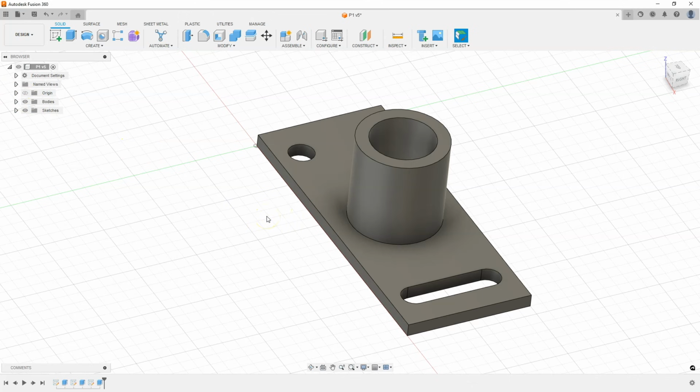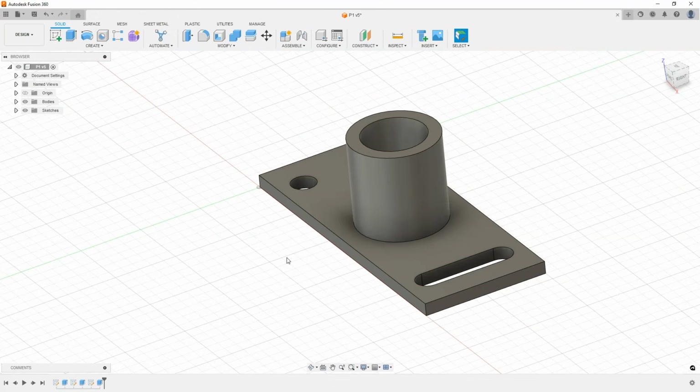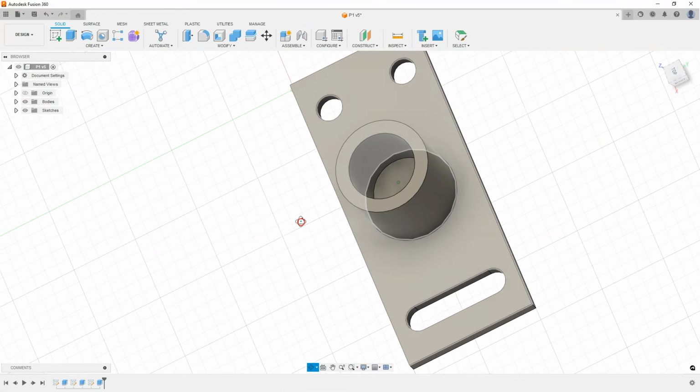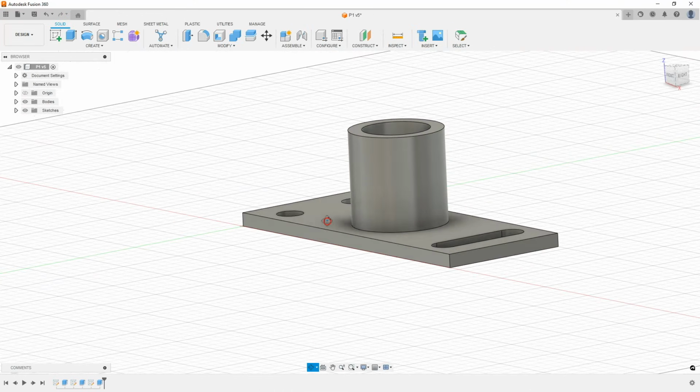And cross-section analysis can be very useful, but let's get back to the hole in this solid. After changing the extrusion length of the cylindrical part, the hole is no longer throughout the entire solid. And if you want the hole to be through all the time, regardless of the height of the solid, we can do it very easily.